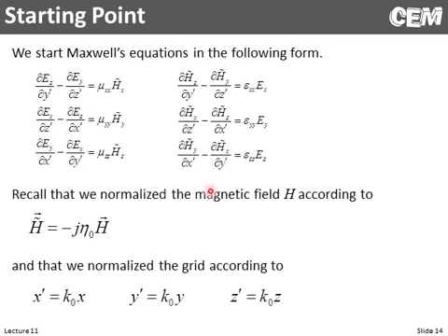But this is our very, very typical starting point. No approximations really have been built in, other than at this point we're assuming diagonally anisotropic materials, but almost all waveguides just contain standard isotropic materials, so in fact we can use this without an approximation. If there are anisotropic materials, this needs to be modified a bit.